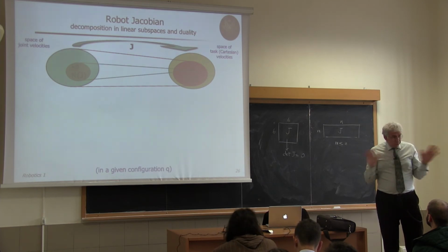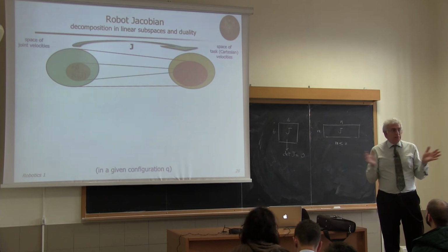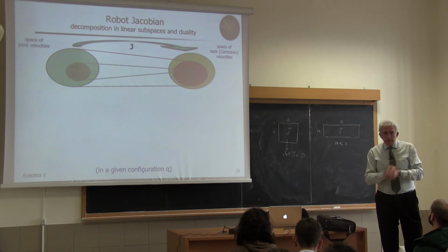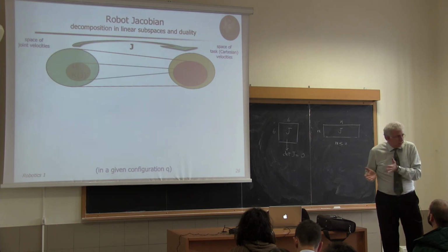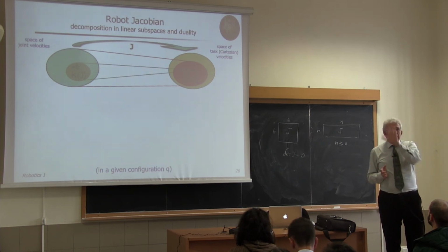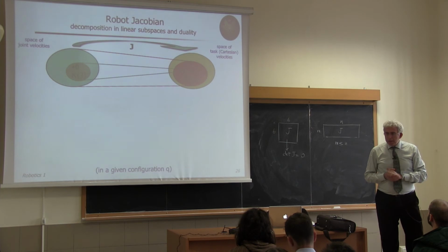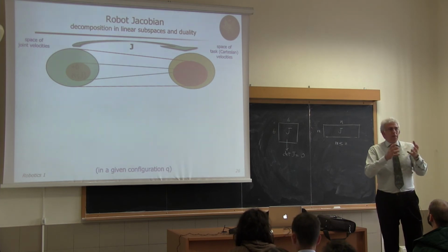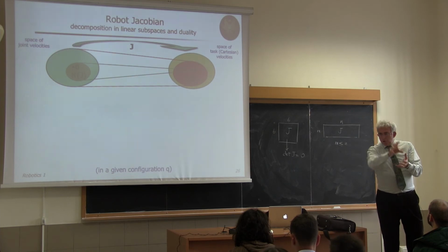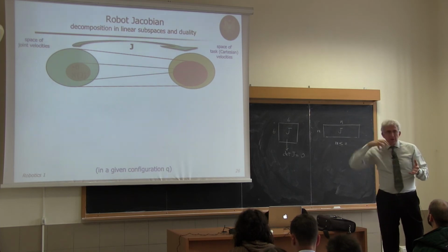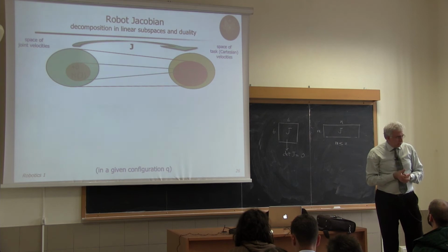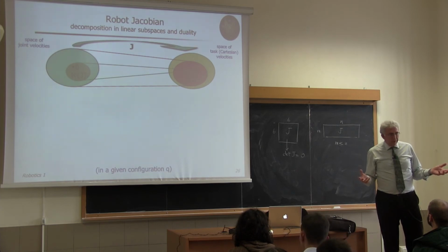So this is fundamental, because not being capable of moving the end effector, although I can move the joints at any place, but the end effector can move only in some subset of directions, means that I cannot, for instance, take an object which is close to the end effector in that direction. I should change configurations and do something else. So it's very important for programming, for controlling motion, for anything that I can do. Okay? In fact, crossing this singularity is critical.